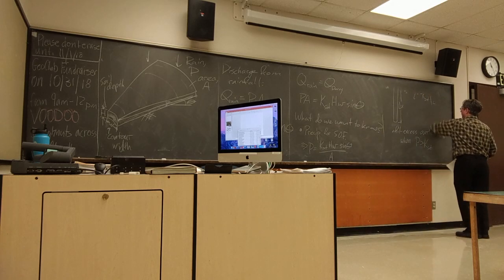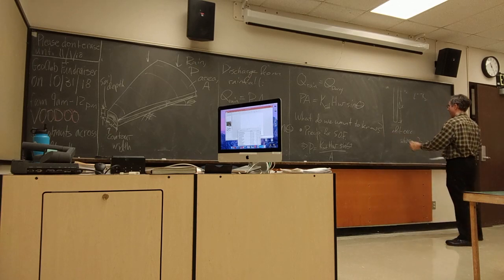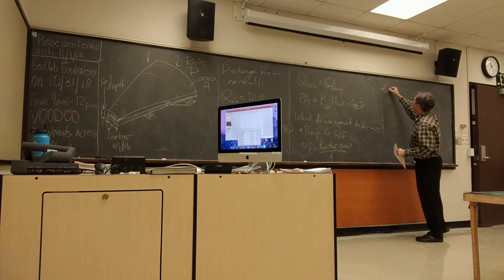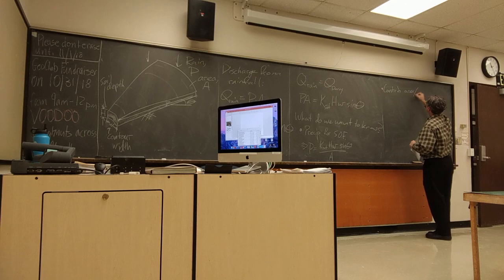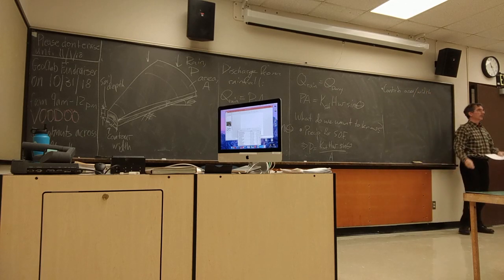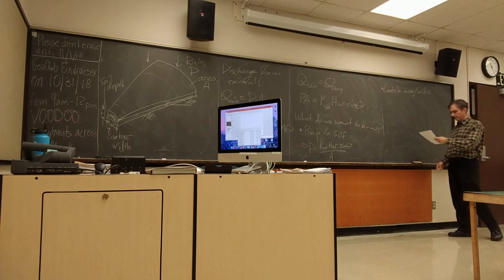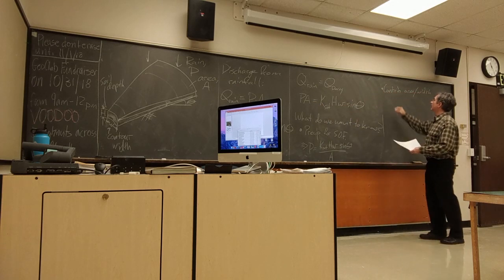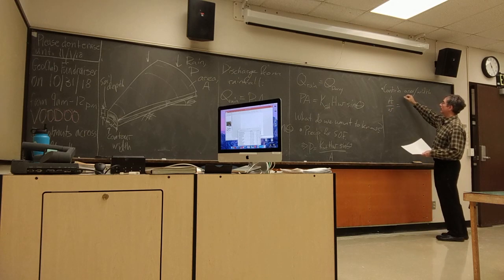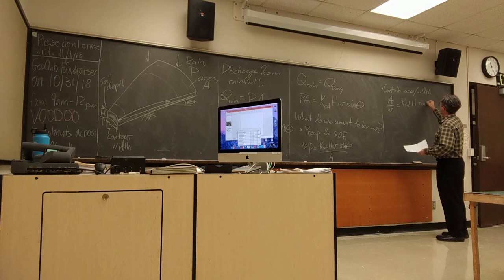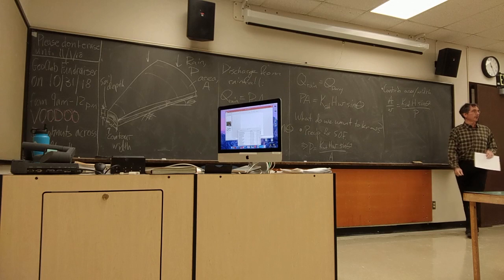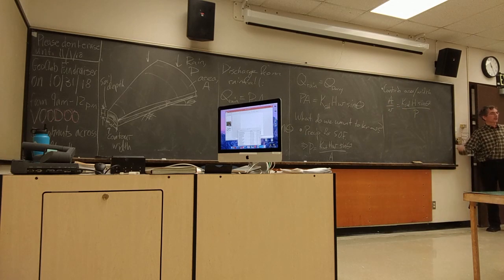What else might I want to know? I think I mentioned last time, maybe I want to know the contributing area per contour width, given everything else, given a certain precipitation rate and so on. Again, real straightforward to solve. All I have to do is divide both sides by P and W, and I get A over W equals Ksat times H times sine theta over P. Larger precipitation rate, smaller necessary contributing area per contour width. This has units of length, by the way, necessary to saturate. Okay, so that makes sense too.